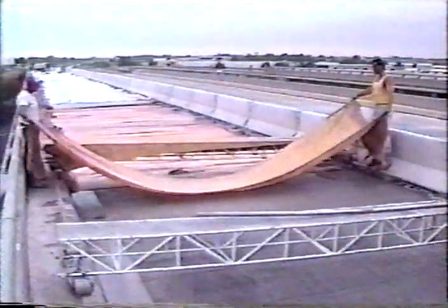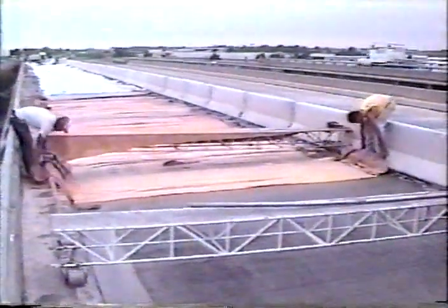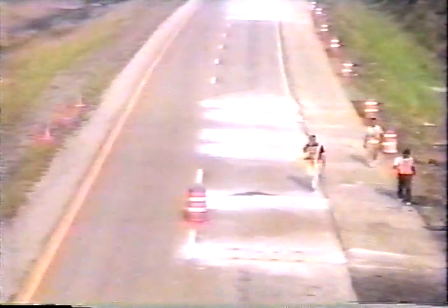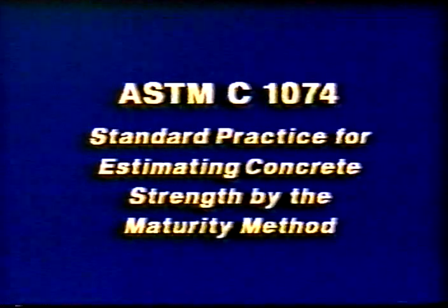The strength of new concrete increases significantly with increasing curing temperature and age. In-place strength can be used as a criterion for opening bridge deck overlays, pavements, or full-depth patches to traffic. Strength development with time is typically different under laboratory isothermal and moist curing conditions than under a range of air temperatures in the field. Maturity monitoring, according to ASTM designation C1074, is used to estimate the strengths of laboratory specimens under non-standard temperature conditions.